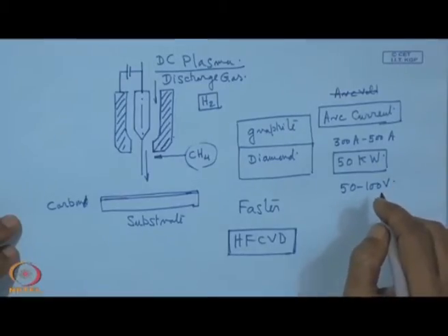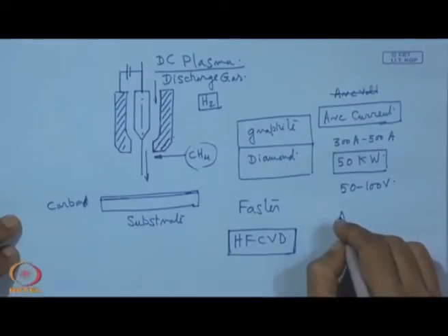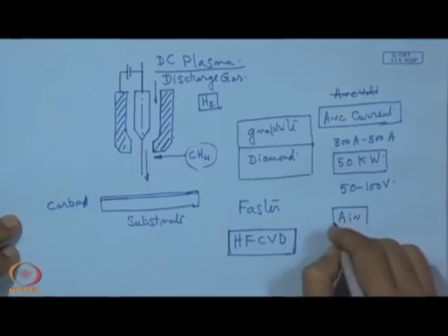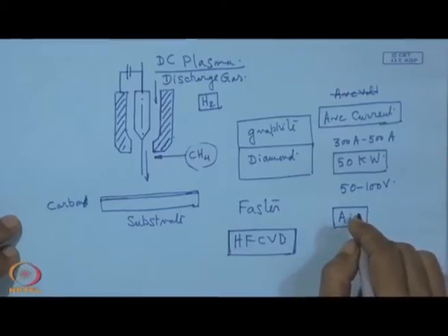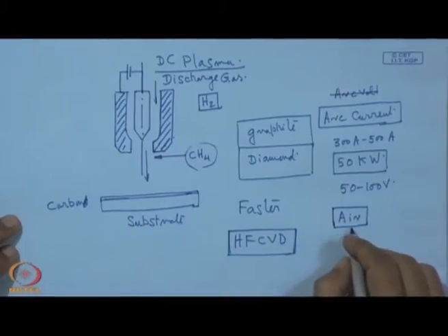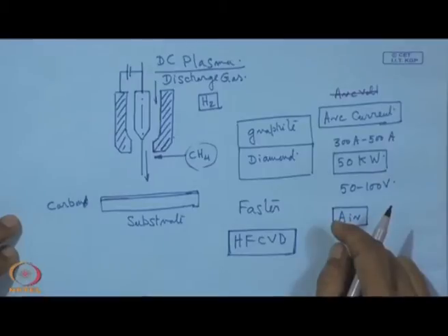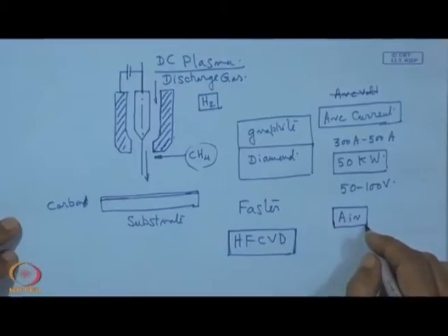Normally powder is fed by air as the carrier gas, but here the quality of air is also one important issue, and this air has to be number one, because the source of air will be a compressor, and the air which is delivered by the compressor should be filtered of all sorts of oil, which may be contamination from the compressor, then this filtering is followed by drying in an air dryer.